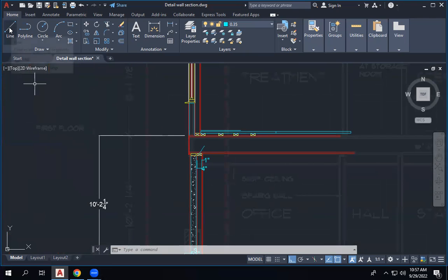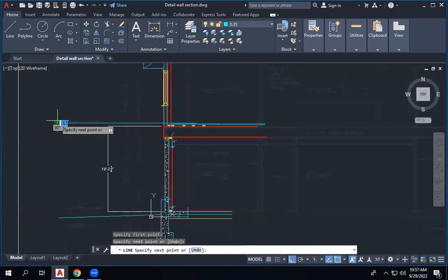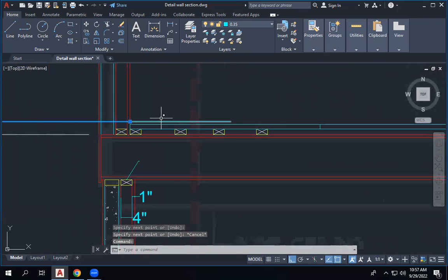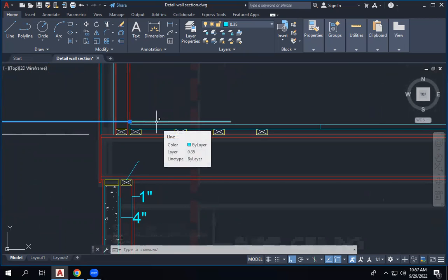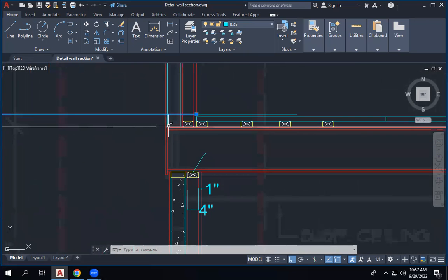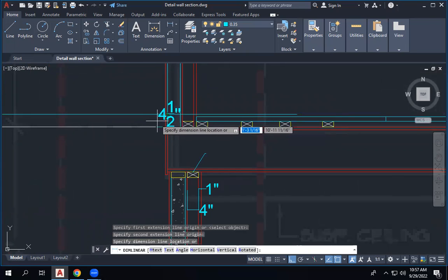So when we give the drawing, we give here as the level. In the drawing, we mark the level on. We give the finished floor level, is actually this level. This is the structural engineer's floor level. So our finished floor level is 4.5 inch from his normal structural level.